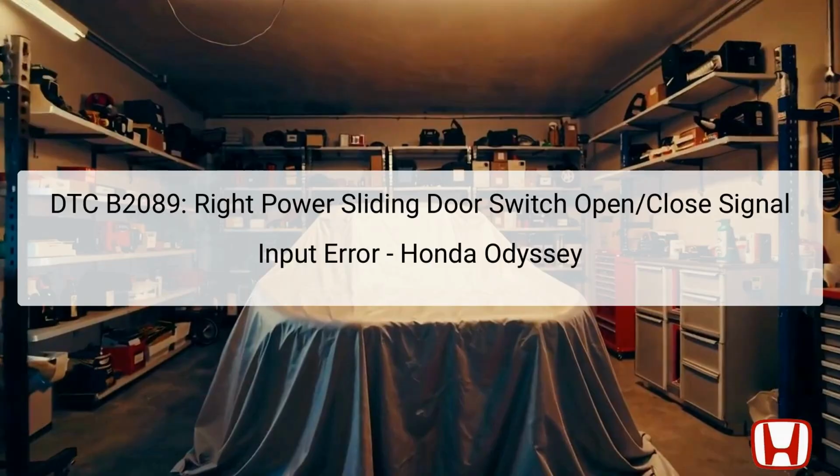The diagnostic trouble code DTC B2089 indicates a problem with the right power sliding door switch in a 2011 to 2017 Honda Odyssey. This error specifically points to an input error where the switch signals for opening and closing are activated at the same time, leading to a conflict in the system's ability to operate the sliding door.